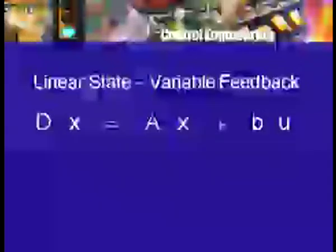dx is equal to Ax plus Bu, and let us say for the moment we leave aside y, we look at the full state vector x. Let us say we are interested in each and every component of the state vector x. Now, as I said just now, if you look at the response, that is the solution of this, then it can be split into several parts, one which depends on the initial values of x and the other which depends on the input.